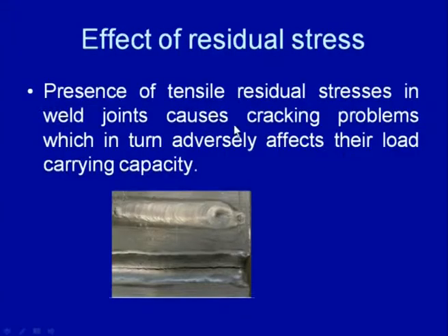We can see the presence of tensile residual stresses in the weld joint frequently causes cracking, maybe at high temperature or low temperature. The cracking occurring at high temperature is commonly known as hot cracking, and it is mostly encountered in the weld joints of metal systems having a higher solidification range.